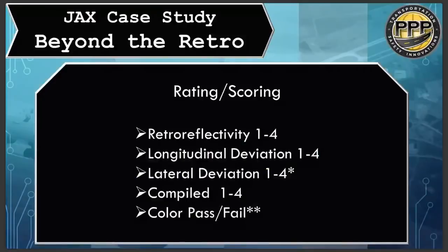So what we did was we said, okay, let's get retroreflectivity, and we're going to put it in our 4 buckets. Remember, we had those 4 buckets earlier. Understand that those are all customizable. So if your airport wants to hold a higher standard than FAA, you're more than welcome to. In fact, in the highway industry, FHWA's numbers that they're going to submit soon are far lower than most states. About 25% of the states now have their own minimums, and they're going to maintain a much higher minimum than even the FHWA. So you can decide what those are.